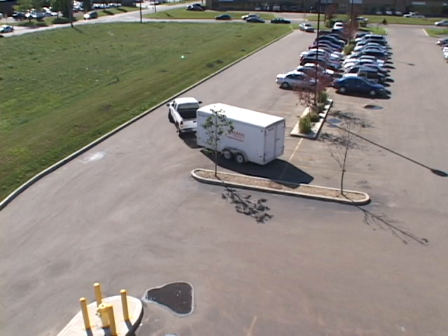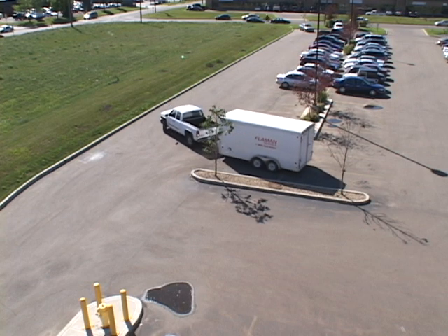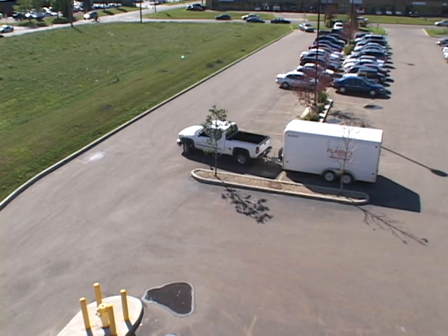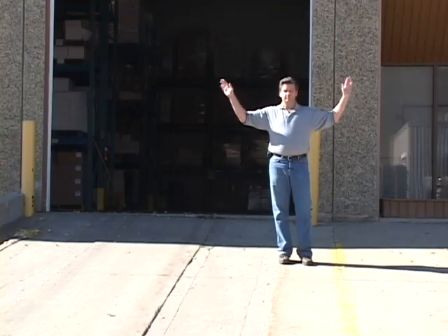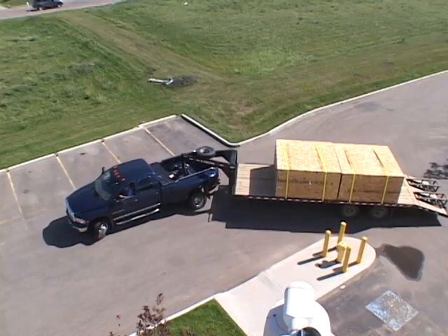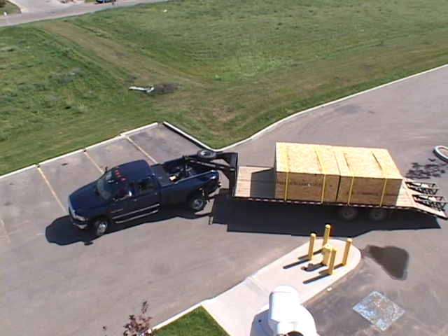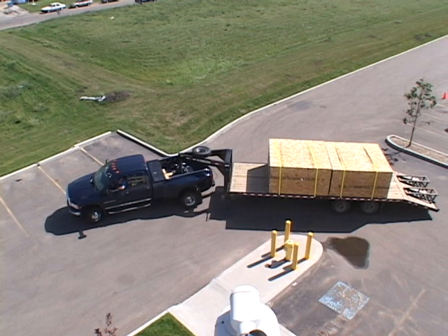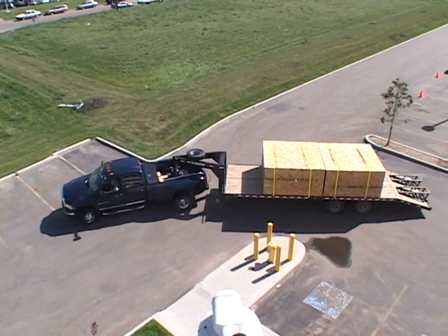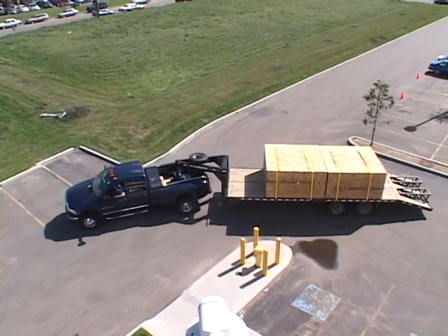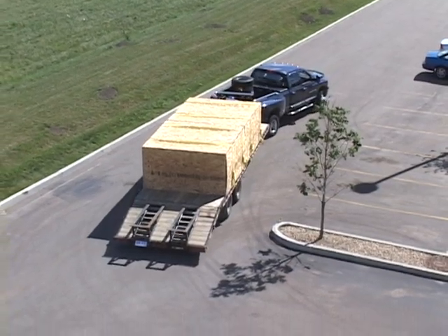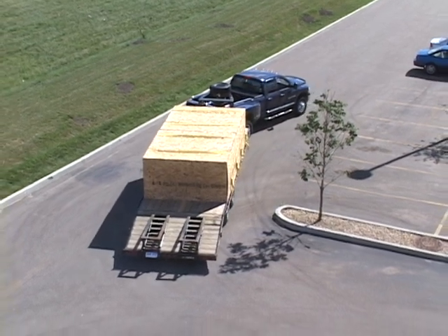Backing a trailer is perhaps the most challenging aspect of operation of a trailer-vehicle combination. First, always check the area you're about to back into. Wherever possible, use a spotter to help with backing. Always be aware of vehicle and trailer swing, and remember it's always easier to back in from the view side. Back up at a slow walking speed. And last but not least, avoid backing whenever possible.